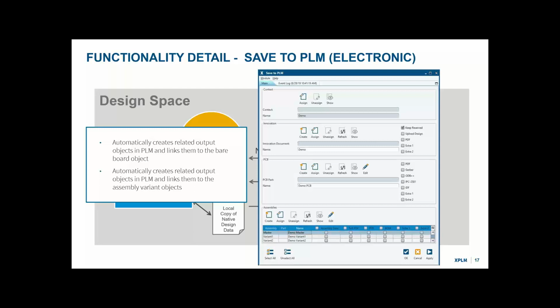For sure. And then what about the, hopefully I'm pronouncing this right, the Altium project file? Yeah, that gets zipped up and put into the design container. That project file is one of the reasons that if you were using Altium, we'd probably try to steer you away from 2-zip and stick with a single zip approach. Some of the CAD tools are better tuned to work with the schematic and the PCB being done independently, like the Cadence Allegro flow. You can easily separate out the Allegro BRD file. But with Altium, both the schematic and the PCB kind of want to write to that project file. So we'd probably recommend a single zip approach to handle that.